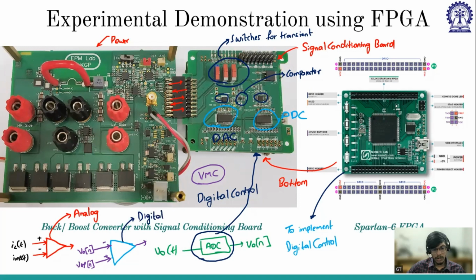Sir, initially we discussed that we have four capacitors at the output of the buck or boost converter. Initially it was said it is to reduce the ESR. Yes, effective ESR will come down. Also it is said the higher the capacitance value, the ESR also will be high. If you connect them in parallel, then the effective ESR will be reduced. No, sir, I'm talking about an individual capacitor. Yes, for an individual capacitor, if the capacitance value is high, ESR will also be high.